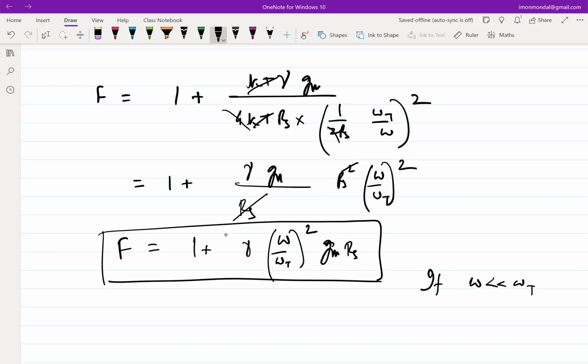Right? So this is a judgment call based on which algebra is simpler. But if you have to give your LNA to somebody, then you have to give the input referred model. There is nothing you can do. Right? So now, as a designer, this is a good thing here because it looks like I can get substantially lower noise figure with respect to the other configurations.